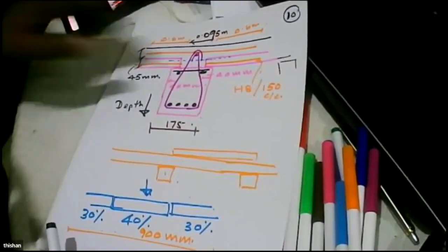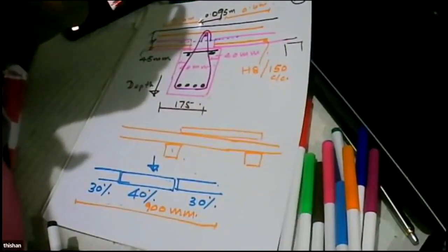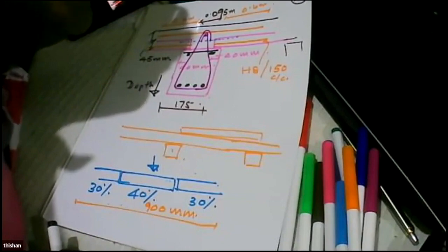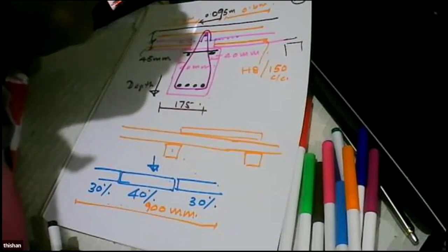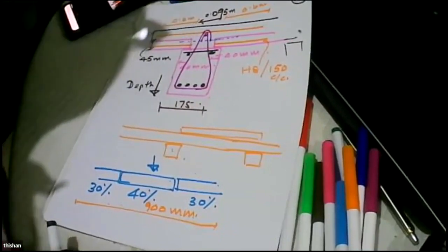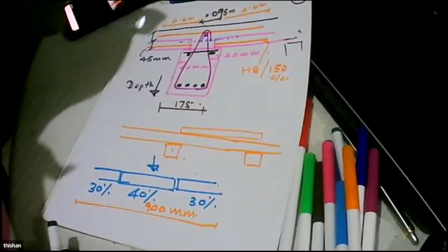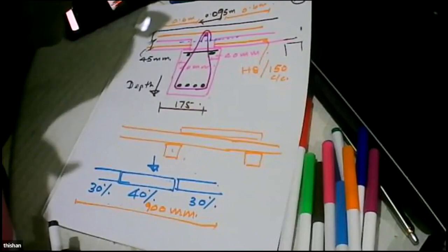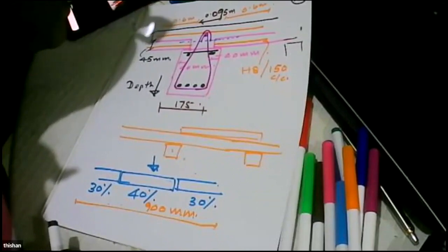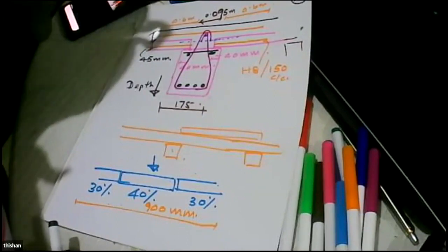One more question, sir. What about the reinforcement covering? As it is less than 20 millimeters, will there be any issue with durability? No, we selected 15 millimeters as the minimum according to Eurocode, because we are using high strength concrete. And this is very high strength concrete, compacted very well. We can easily cure the steps because after about 24 hours you can make it vertical and then carry it. Okay, clear, sir.